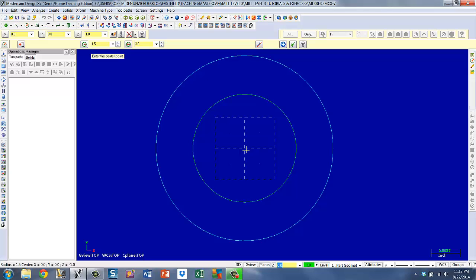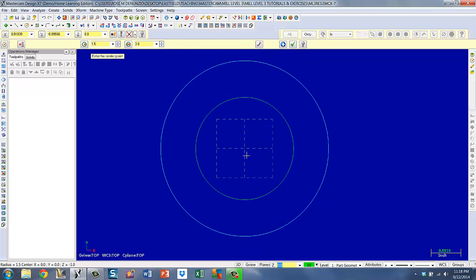I think the next thing I can do to build anything would be to put in the angled lines, the 35-degree angled lines. So I'm going to check out of that operation, go to the shortcut, create line endpoint. This needs to be a negative z as well. It says specify the first endpoint. I'm going to start from the origin.